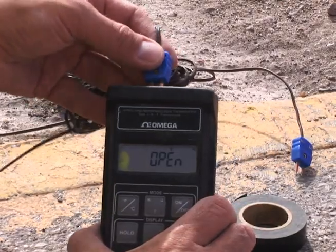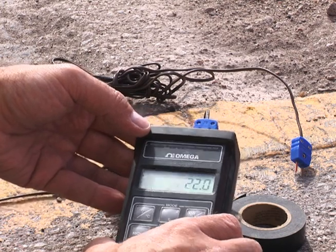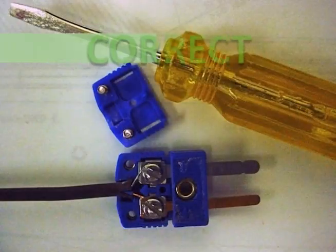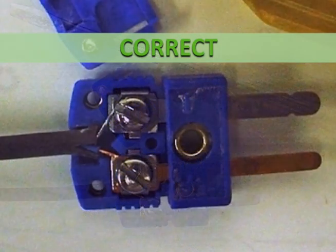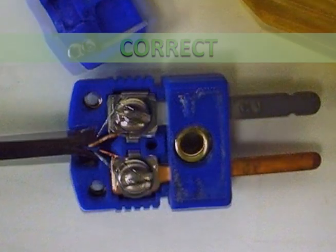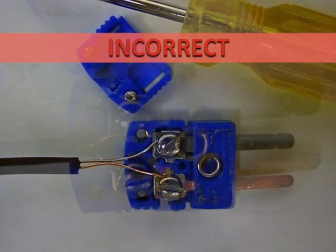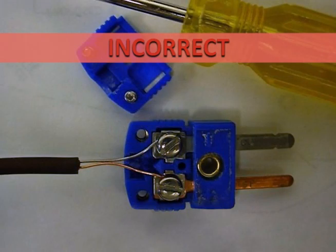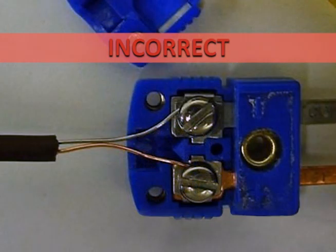The preparation of the thermocouple wire is extremely important for successfully acquiring temperature data. This is a correctly prepared mini connector and wire. The wires are attached to the correct screws, nickel to nickel and copper to copper. When the wires are connected to the incorrect screws, it will cause an inaccurate temperature reading. This shows an incorrect wire assembly due to the wires being too long, causing the wires to touch. This will also give an inaccurate temperature reading.